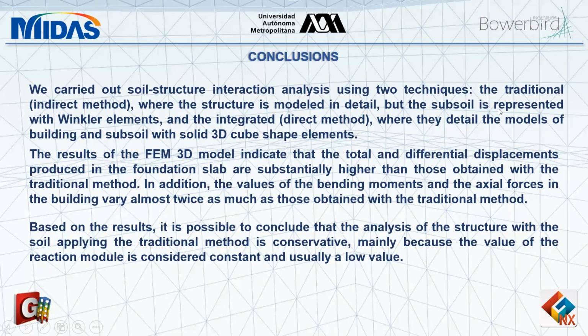So in conclusion, we've carried out the analysis with both techniques: the traditional, aka indirect method, where we use the Winkler spring elements for the soil, and then of course we compared that with the exact same structure and loading conditions for the direct method, or the integrated method. And we looked in detail at where the soil was modeled as 3D shapes.